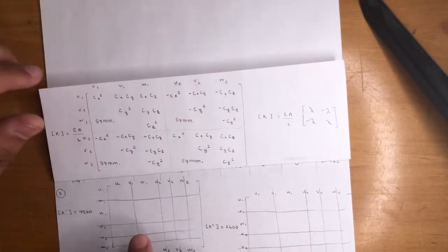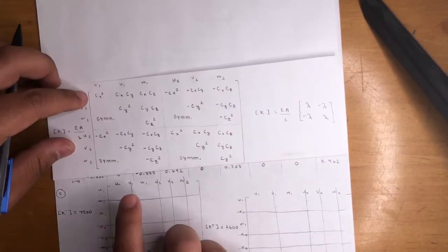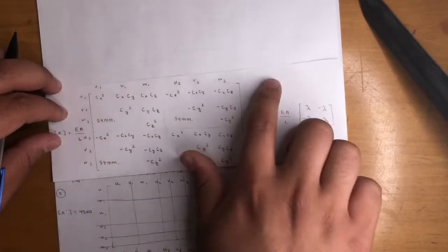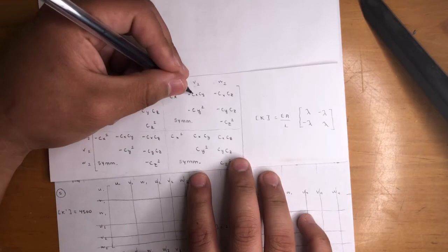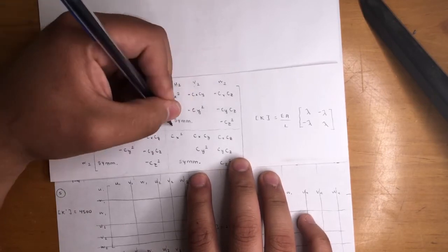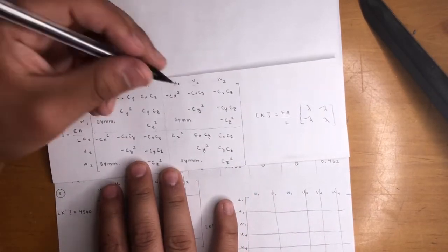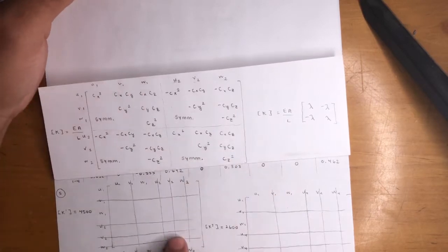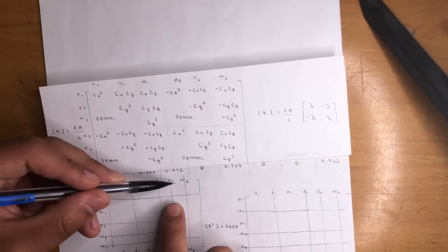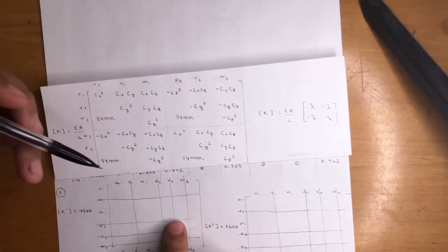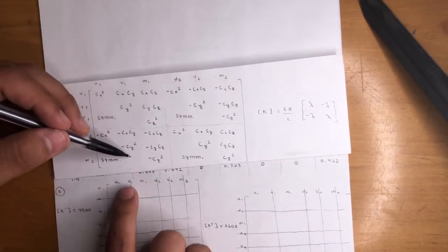So you see how this is for each element. This is the stiffness matrix for each element. That's what we have here, right? It's a 6 by 6. We would have normally filled every single position. What symmetrical means is this goes here, this goes here, this goes here. Same thing for all 4 of them. Just be careful with the signs, right? But because we applied the boundary conditions, let's just focus here. So these last 3 columns are gone. We don't care about them. All this is gone, the last 3 rows. This one's also gone, V1, remember?